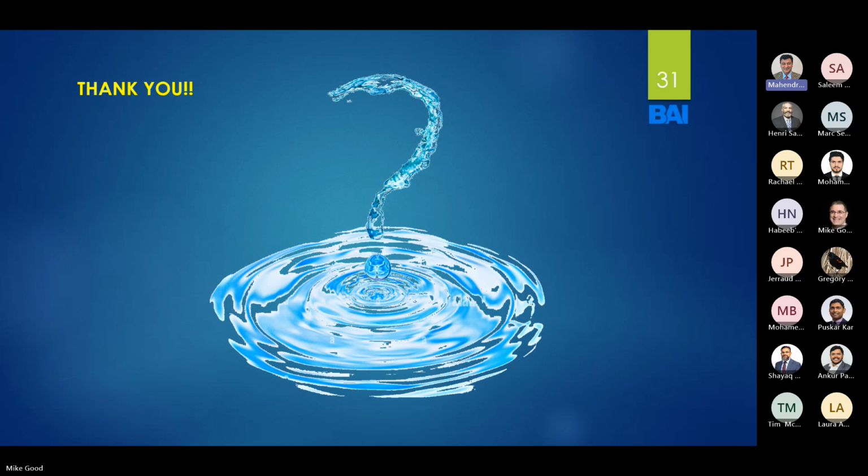In the earthquake-prone zone, whatever we provide for the stream flow scour, the liquefaction scour comes into play, because when the earthquake vibrates, groundwater comes up and liquefies the soil. In that case, do you know what would be the best option to prevent the liquefaction scour of the bridge pier? I know in Japan and a couple of places they commonly use grouting. Is there any other measure in your mind?